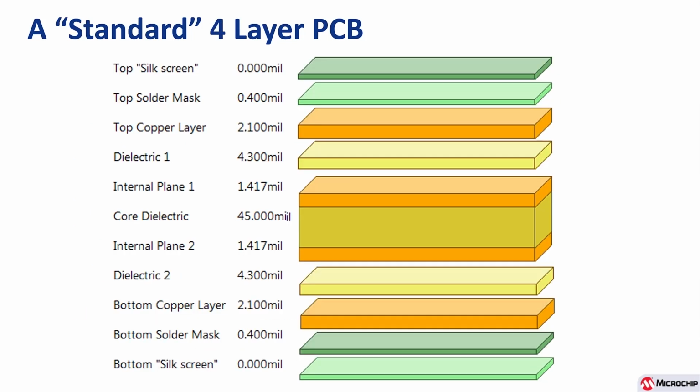A more complex four-layer board might look like this, with the center core pre-laminated and completely cured, and then semi-cured layers of dielectric added to that, and then copper foil and the other layers. All of it gets squeezed together or applied later and turned into one solid board.